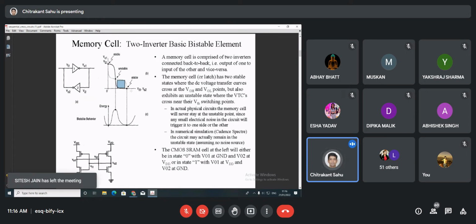So if you measure one edge, suppose in terms of voltage it is one, and 5 volts is the maximum voltage, so maybe the edge will come to around 1 volt. So 1 volt will be the noise margin of the particular memory element. This way we can derive the noise margin of the device using the butterfly technique.